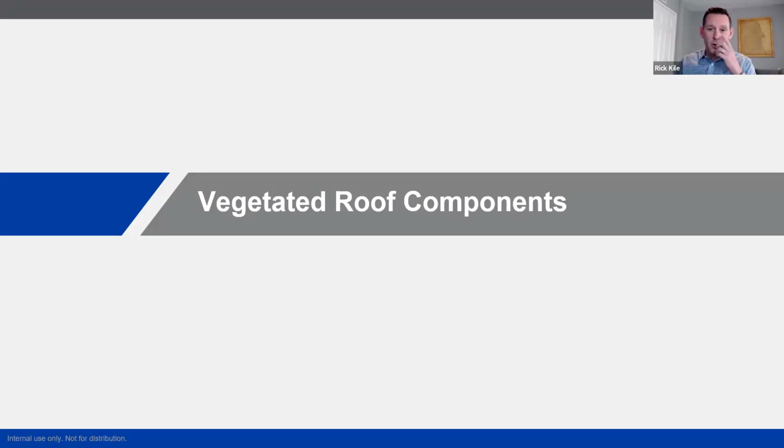Yeah, so there are different compressive strengths available for polyiso, for the cover board that might be associated with the polyiso. If it's an extruded, there's 25, 40, 60, 100 PSI. 25 is typically a roofing application, 40 we'd use in vegetated roofs, 60 we'd use underneath pedestal pavers, and 100 you're using under a drive aisle. So it really just depends on the application and what density. Geofoam or EPS has a similar story with regards to different compressive strengths depending on the application. So that's a project by project basis recommendation.